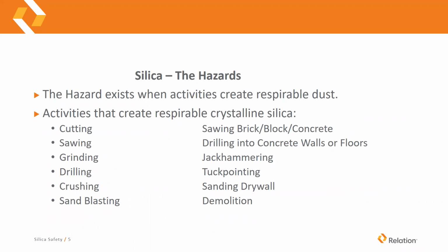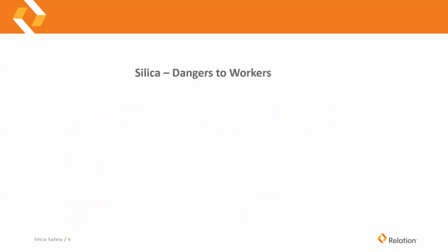So the hazards of silica. The hazard exists when activities create respirable dust. The activities that create this are cutting, sawing, grinding, drilling, crushing, sandblasting, sawing brick, block, or concrete, drilling into concrete walls or floors, jackhammering, tuck pointing, sanding drywall, and then some demolition activities.